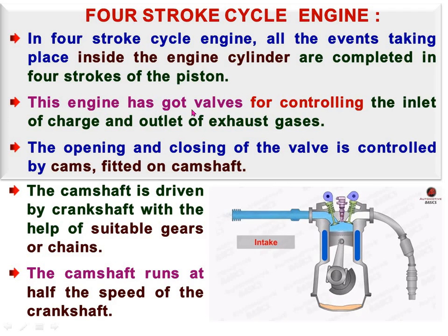This engine has valves for controlling the inlet of charge and the outlet of exhaust gases. This is the inlet valve. The inlet valve opens at the time of the suction stroke, or intake stroke. This is the intake stroke, during which this valve is open and the exhaust valve is closed.